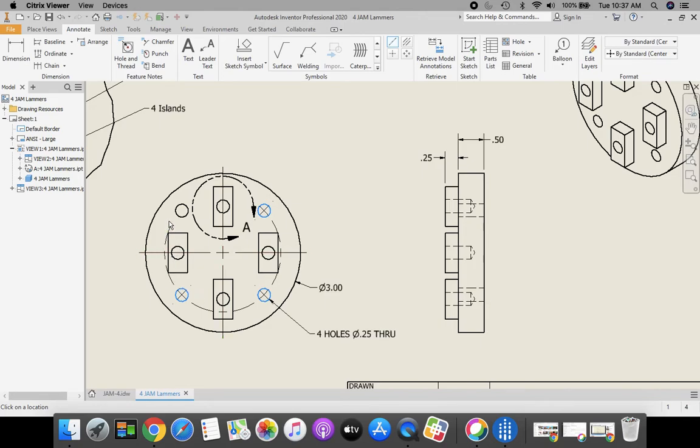Do you see that? Click my fourth hole, and then with your mouse tool on an iPad, or right click, click create. Remember, you have to do that with your iPad. You have to go up to that shade at the top in order to get your mouse and then use the right click feature on it. Now we have our bolt hole circle on there. We have our center mark. Now we can identify some of these other ones.